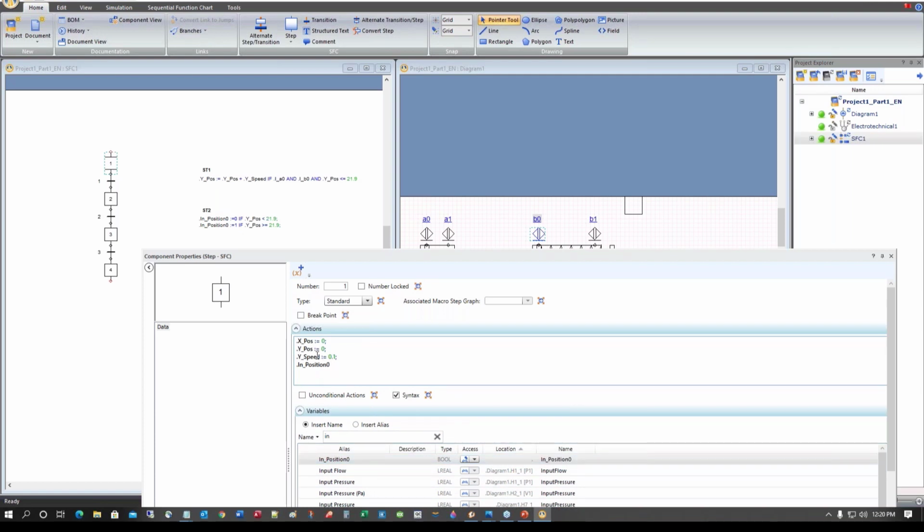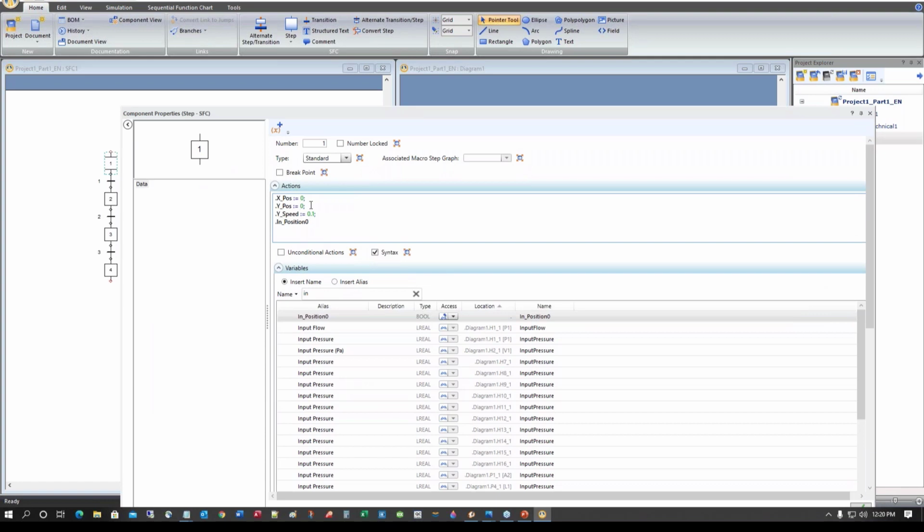Look here, it's very important to notice in the graph set the assignment, or associating a value to a variable. If this variable is real, there is the equal sign, the assignment sign, and there is a space here. For a Boolean, it's going to be equal, and this is syntax, it has to be stuck to the equal, no spaces over here. If by any chance I put a space, you see right away the validation, there is a continuous validation of the syntax in the graph set that will show me that the instruction here is not green, it turns red or purple, which means that there is an error here. The error is because this variable is a Boolean, and to initialize it, I have to give it a Boolean value. So this is the assignment way. In a Boolean, it's going to be either 1 or 0. So this is right, okay.